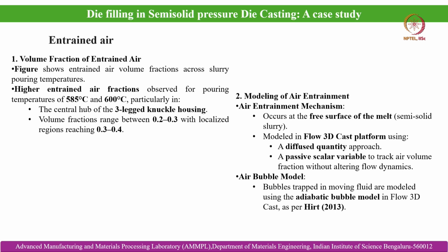And so the findings on entrained air. We have discussed in the former classes of this section that it is very important to consider gas absorption and air entrapment in case of die filling, because they are responsible for pore and bubble formation within the solidifying component. That in turn makes the structural integrity of the components weaker, and it also serves as potential sites from where cracks nucleate and lead to catastrophic in-service failure of these components.